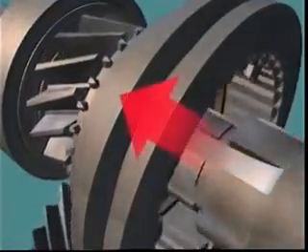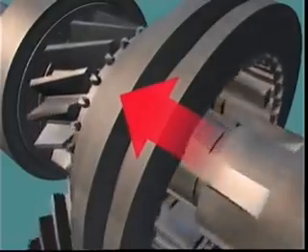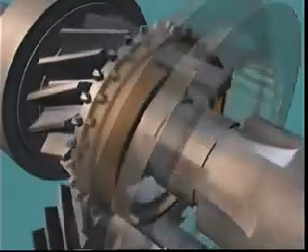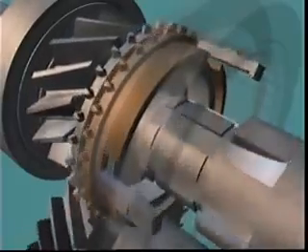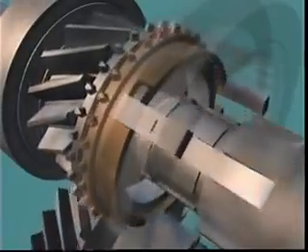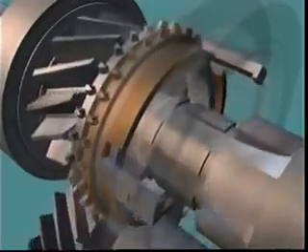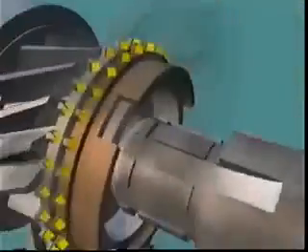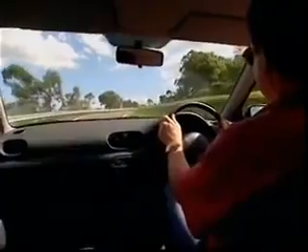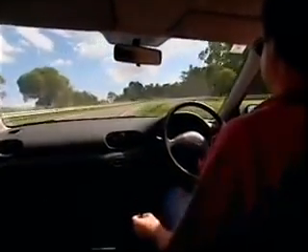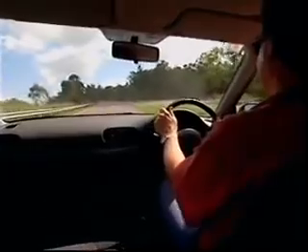The force exerted by the driver now presses the sleeve against the teeth of the balk ring and forces the conical face against the cone of the selected gear, until the friction created causes the two components to rotate at the same speed. The balk ring teeth can now come into alignment, and the sleeve slides over them and into engagement. This is assisted by a chamfer on the teeth, which helps to guide the sleeve into position. Smooth and rapid gear changes are thus ensured.